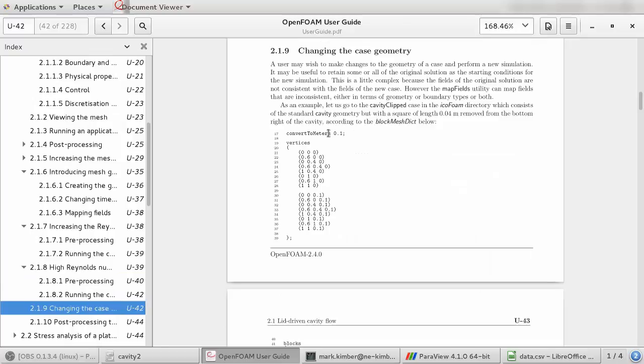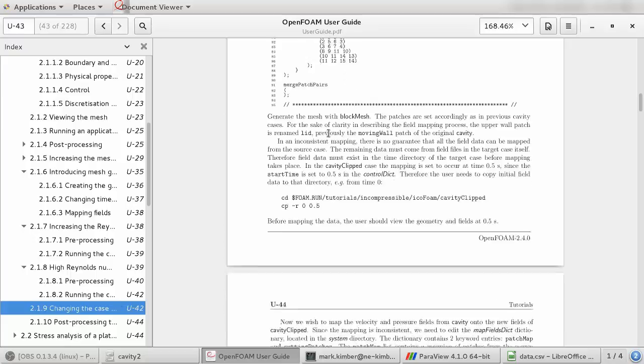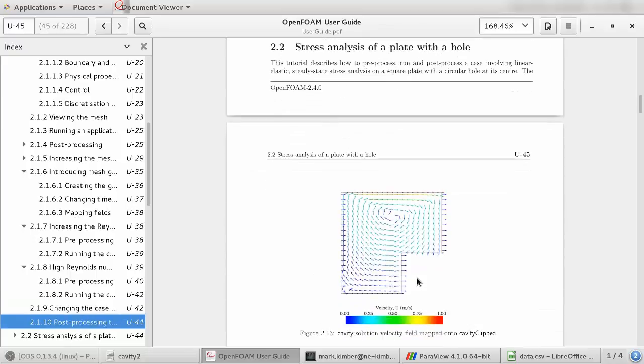And then if we wanted to change the case geometry, in this case, what they're doing is they block out one of the 4 blocks, and hopefully this looks familiar enough to you that you should appreciate what's going on here. If you do the annulus problem that we've talked about in class, or done the homework on, then this is basically a 1/4 model of that. You obviously need to change boundary conditions. So you'll have a bunch of no slip conditions and then velocity in the z direction into the page.